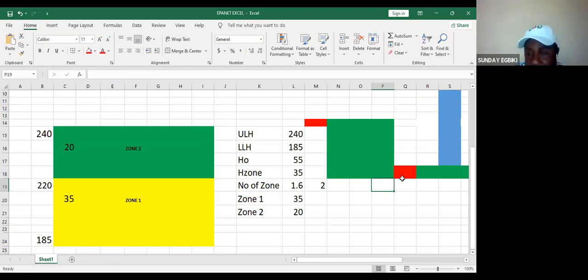And take note of the freeboard. EPANET will also ask you about this minimal water level here, and EPANET will also require the initial water level in the tank. You know, the water in this tank can never go below a certain point, so there will be some water remaining here, which you can use to flush the tank. So all those values are required.